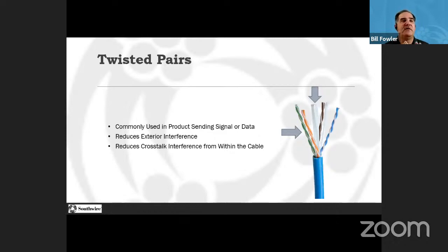So that center divider is very, very important in your higher speed data cables. We really saw that when we got into the category 4, category 5. That's where we saw that center separator coming into play, and making sure that those cables stayed consistent down the cable, and also the distance between each pair stayed consistent. So that's your basic construction when we talk about twisted pairs. So your twist is 1, and that center divider is number 2.